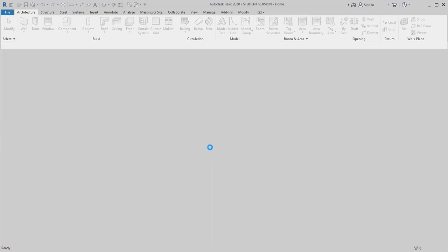As this opens up, let me go back to the fundamental issue that we need to think about when we're using Revit. Revit is a modeling software. The essence of this is we're not drawing lines. You don't want to be thinking about drawing lines. We are actually placing objects. That becomes very important because when we do our setup, we're looking at the different planes.